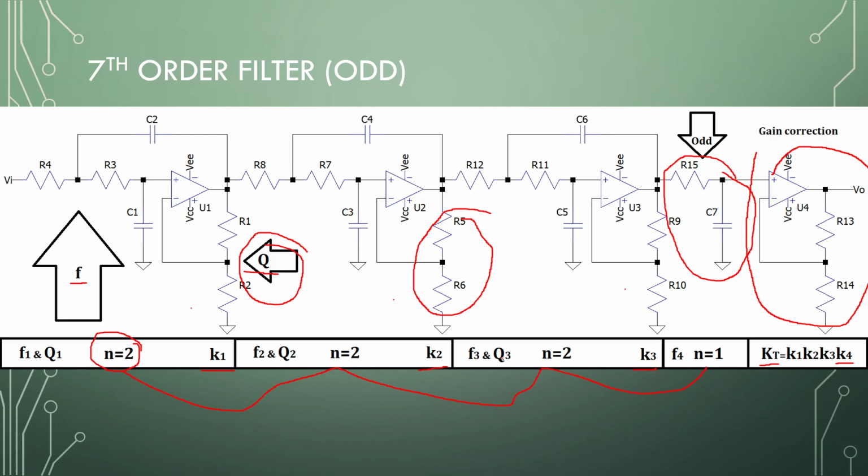You will just raise up the Q factor and perhaps cause some oscillations in the process if you push one of these filters into instability. With Chebyshev, you can already see that there is instability due to the positive feedback and the high Q factors.